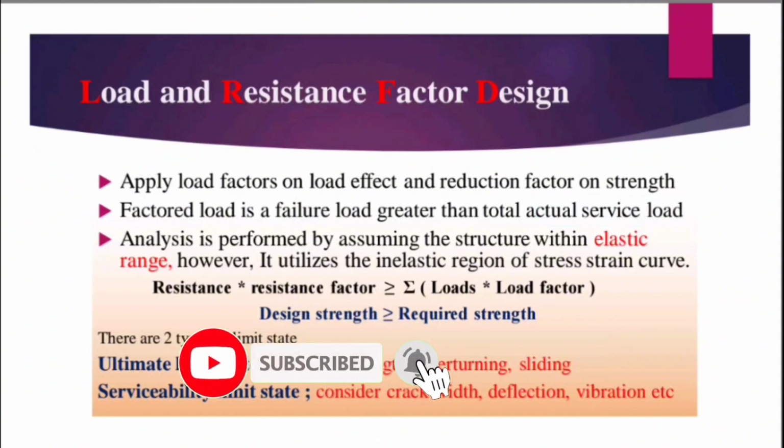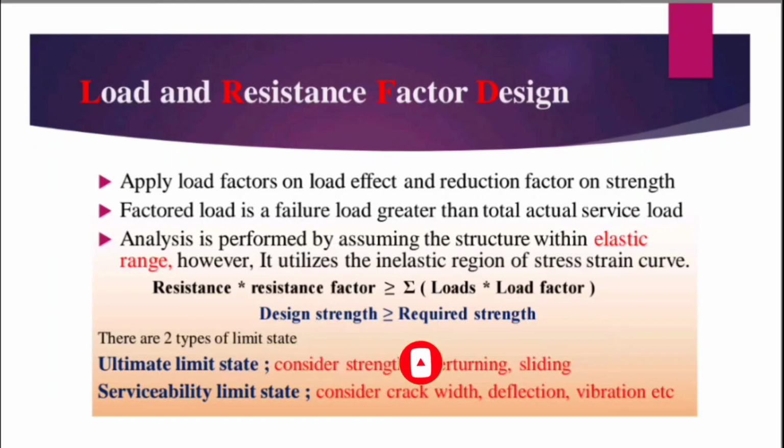So remember this. In analysis, the main assumption of LRFD is that we are using the elastic range. However, we are also utilizing the inelastic region, the plastic region. In ASD we are only utilizing the elastic range.